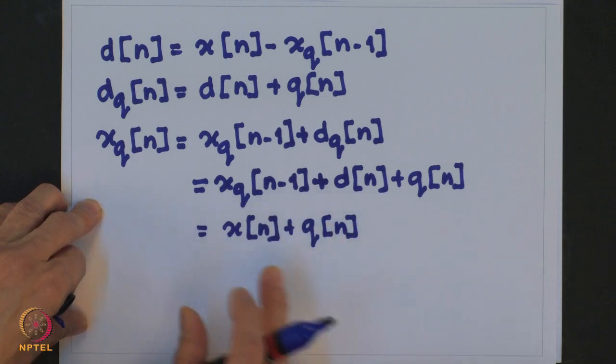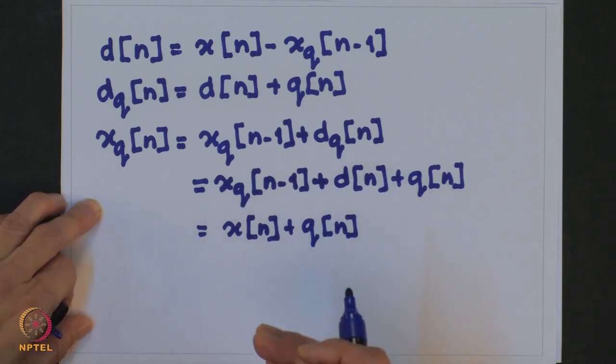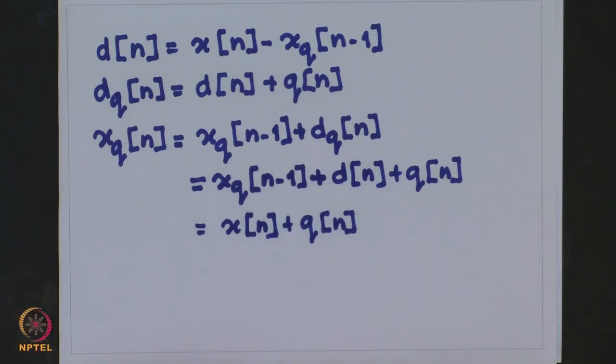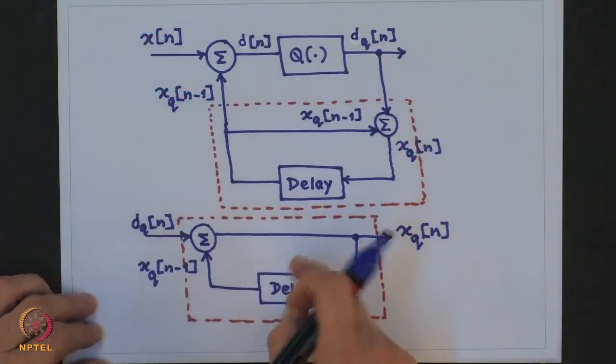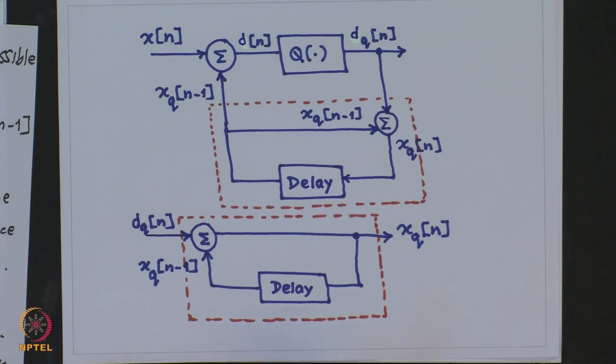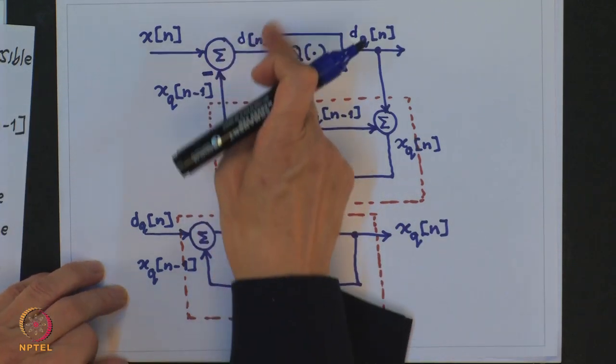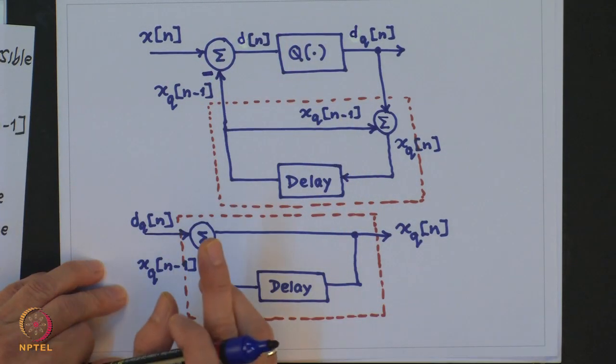So what we could say is that if we are satisfied with the quantization error for a given number of bits per sample, then we can use fewer bits with a differential encoding procedure to obtain the same distortion. Now in our discussion so far, we are using this kind of differential encoding scheme. In this scheme, we would like this dn to be as small as possible, correct.